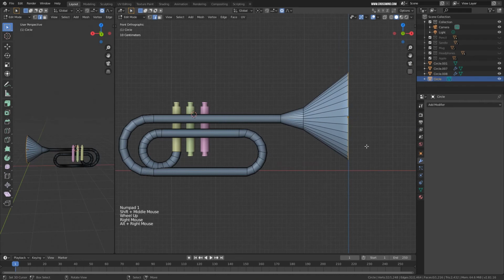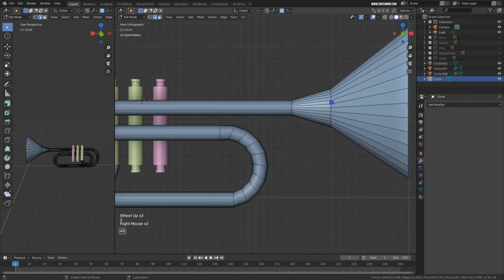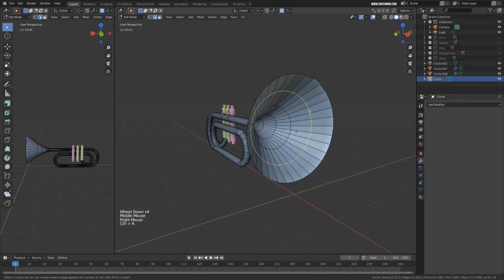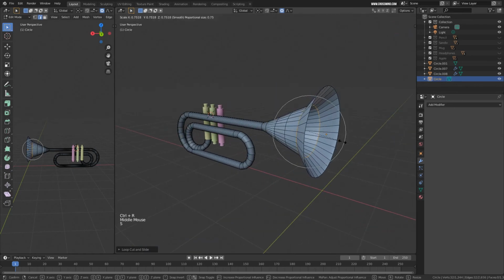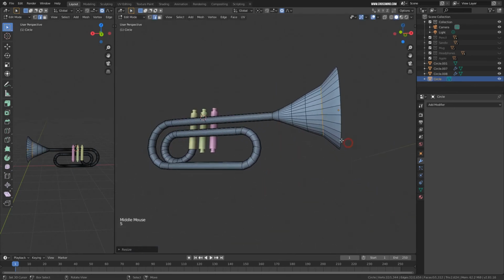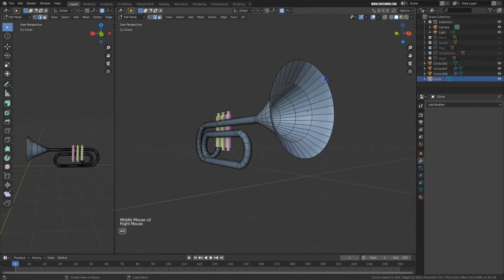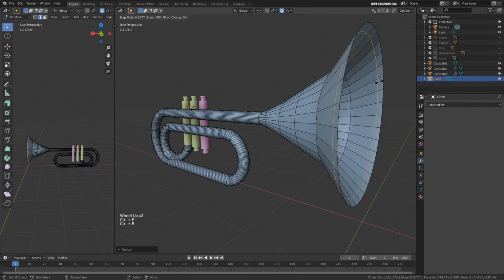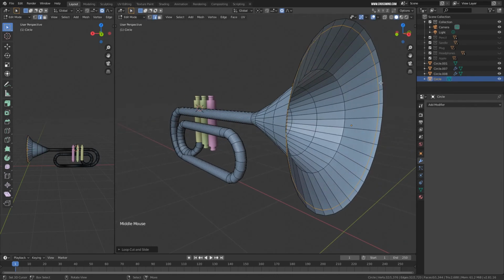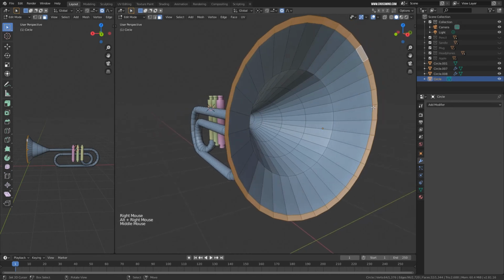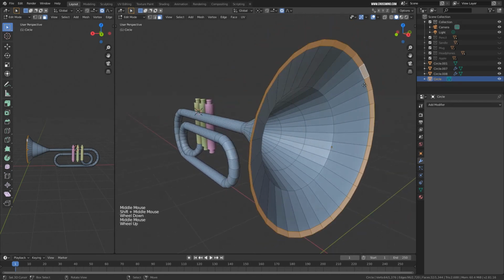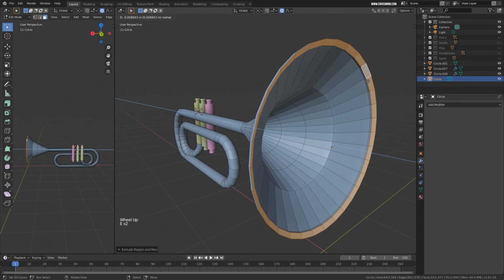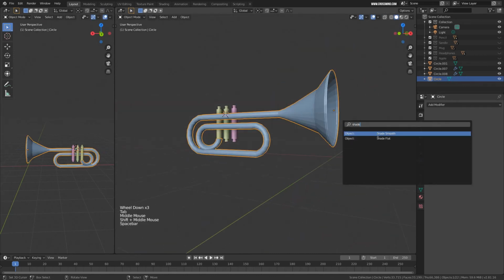All right, so I'll select this area, these edges, and maybe create one bevel over here. And I need some roundness over here. It's looking too flat, and I need a smooth looking transition over here. And then you can create one loop cut here, and with the alt right click you can select this entire area and extrude this out. I'll shade smooth this one.